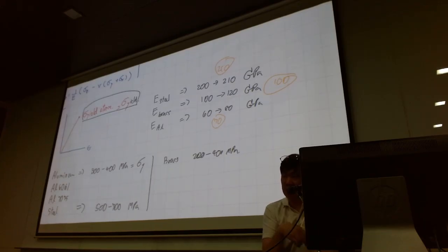But they are quite capable of knowing the mechanical property for each one of those because they have to check against the order forms. The order form would be saying, okay, get the metal that has this kind of strength, and then they do checks with the spec sheets. If it does, then it's okay. Usually, they will be pulling the metal until it breaks. It's a fun thing to watch. So check out the YouTube videos, tensile test, by yourself. Of course, there are several of those.